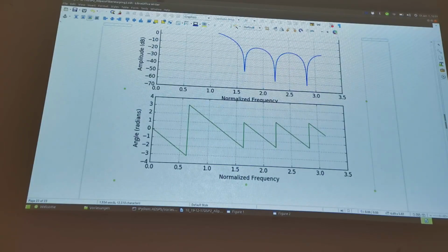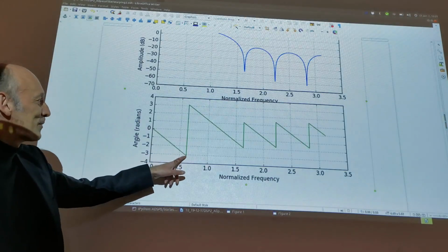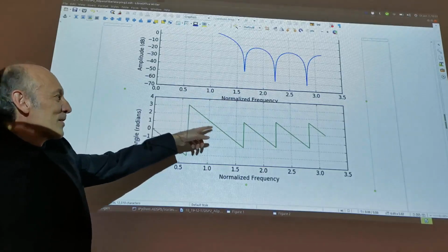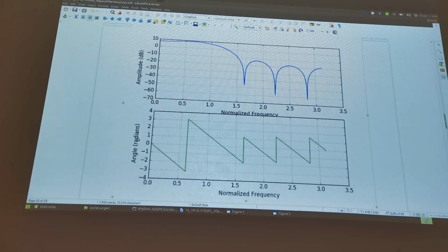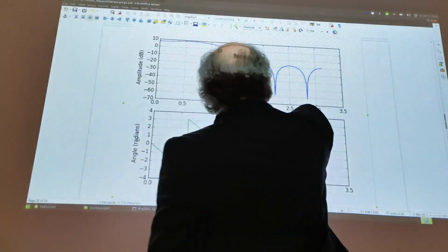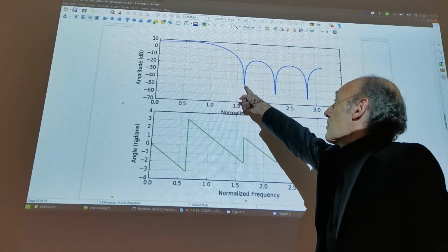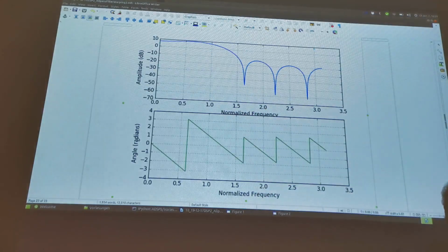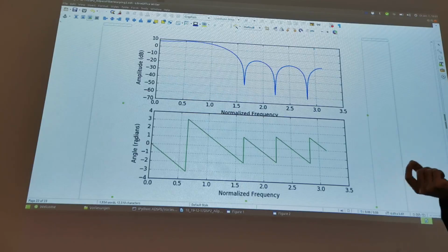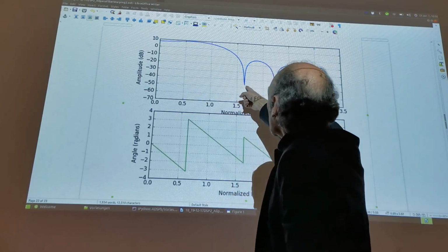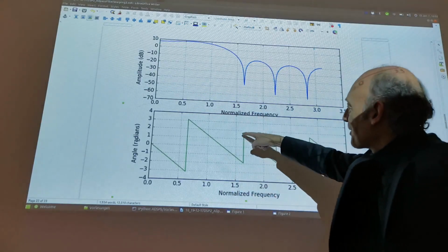So this here, this is what you would expect, right? You have minus pi and you have pi. But then here it's doing the same stuff. An explanation might be this: when you look at the positions where it's doing those jumps in the magnitude, this is basically where the magnitude becomes 0. So you get tiny numbers, and that also means those numbers for the phase are kind of questionable, because what's the phase of 0? So that's why, when you have this magnitude 0, the phase in this area is kind of questionable.